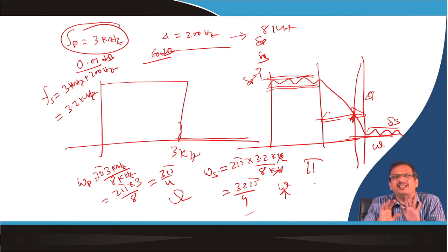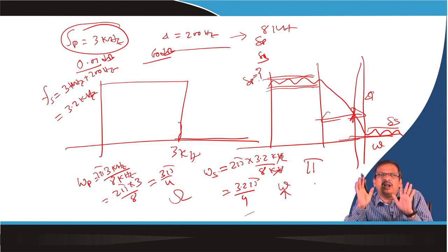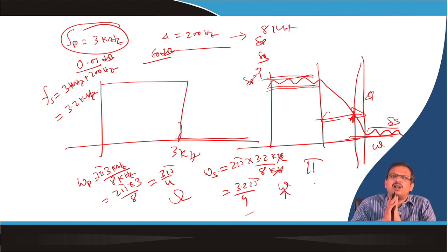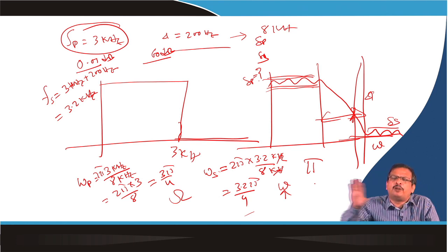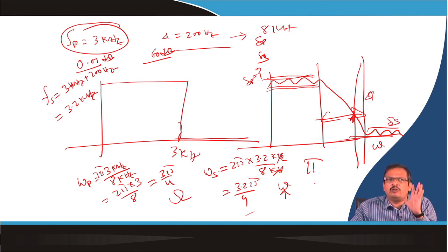Okay. So I think this portion you have understood. What is there? I have to design a digital filter. A digital filter is nothing but an algorithm. So what will be given to me? They will provide a specification of the filter, which will be described in terms of frequency, ripple and transition bandwidth. Now from there I have to derive the filter parameters: omega p, omega s, pass band ripple, stop band ripple, and then I go for the design of the filter.